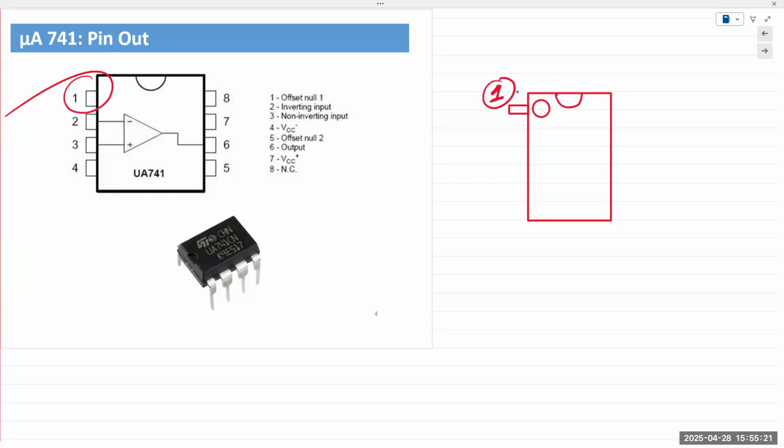Always. Doesn't matter what kind of IC it is, doesn't matter what kind of chip it is, doesn't matter who manufactures it, doesn't matter the number of pins, whether it's 8-pin, 14-pin, 16-pin, 20-pin, 48, 100-pin chip, doesn't matter. That's standard configuration. Always start with pin number 1 on the left. So if you have an unknown IC in your hand, you're trying to figure out the pin out, you hold it like this in front of your face, notch at the top, pin number 1 is to the left of that notch. And then you start counting down in this direction, make a U-turn, and you go up. And that's the last pin right there.